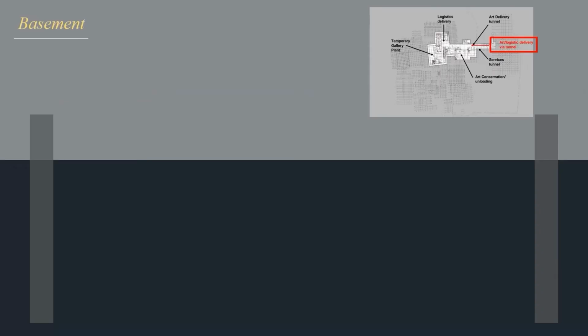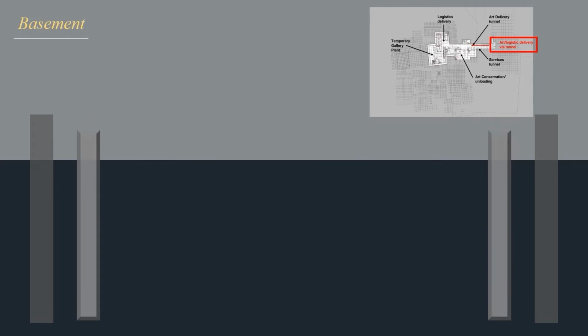Regarding the water, we dug a well at regular intervals along both walls of the trench and did the dewatering. In addition, to prevent the structure from floating by groundwater, about 600 concrete and steel poles were drilled into the bedrock to hold the entire structure in place.